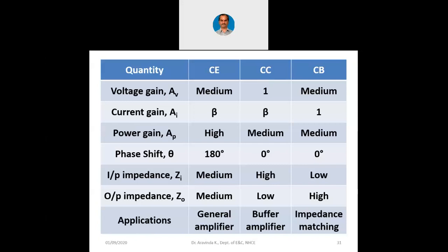Actually, in an amplifier, we require a gain which is more than 100. Actually, we require 1000 or sometimes 10,000 or sometimes 10 lakhs also, because the input signal may be in femtovolt or attovolt. In that particular case, we want voltage gain which is much larger. But then it is not possible to obtain that voltage gain using a single circuit. So what we do is, we connect common emitter stages in series, one more common emitter, one more common emitter, so that we will get a voltage gain which is in thousands or in lakhs.